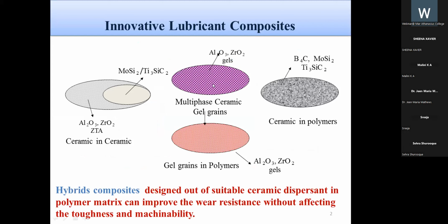There are plenty of opportunities in different strategic fields for oil-less ultra-low friction lubricants that can control noise as well as enhance the performance and life of structural components. Development of such solid lubricants has been strongly taken up in metal matrix composites and alloys for more than decades, rather than ceramics. The reason is that ceramics are brittle and not machinable. Moreover, the high density and high temperature processing are also limiting the development of solid lubricants based on ceramics.